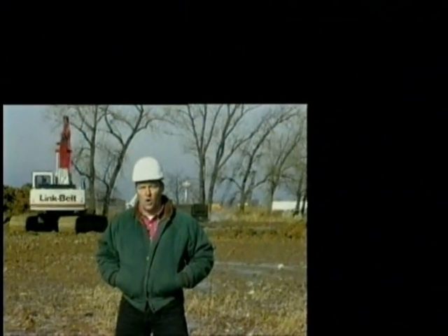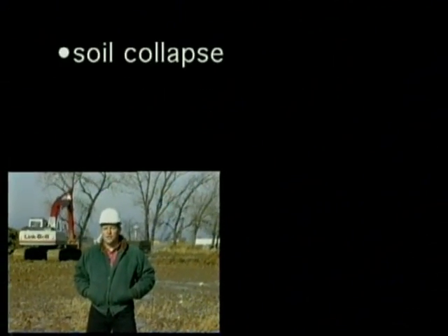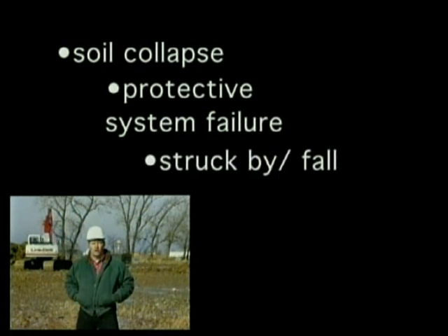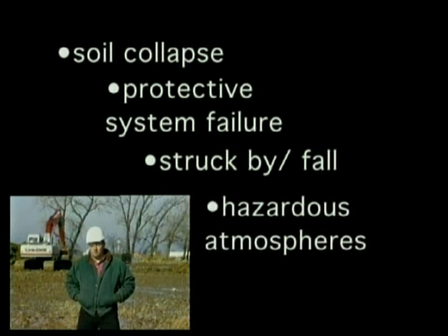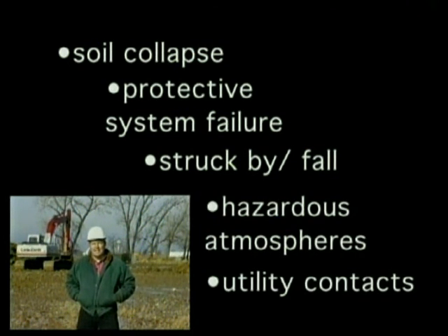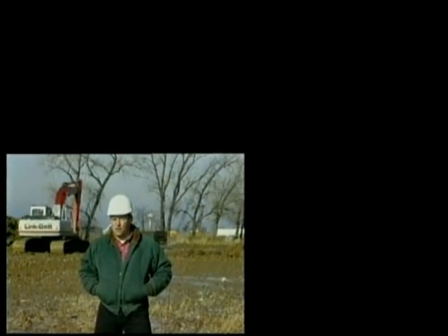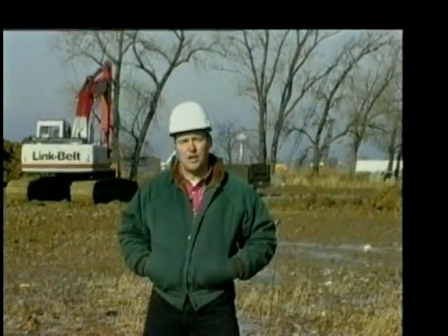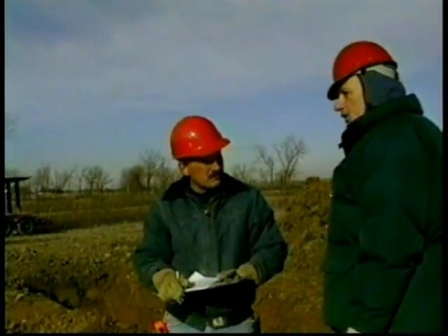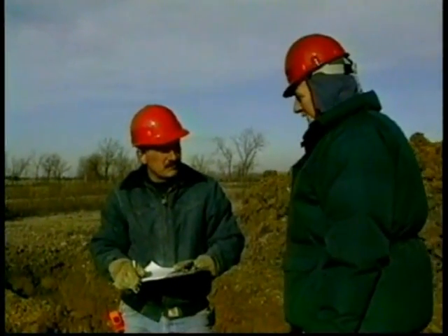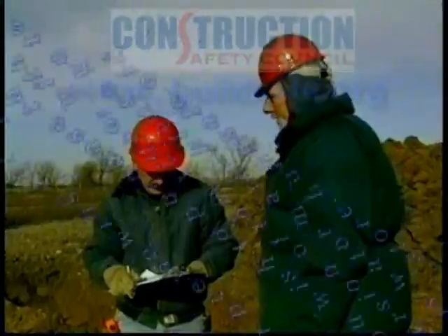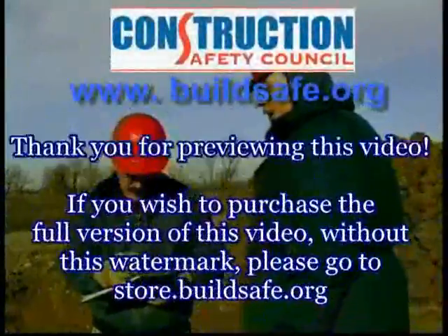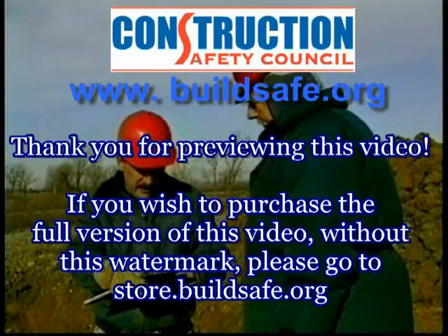Emergency situations usually occur suddenly and without warning in excavation work. Emergencies include soil collapse, protective system failure, material or equipment, or an employee falling into the excavation, hazardous atmospheres, and utility contacts. Because many fatalities occur when workers improperly try to rescue co-workers, every construction site should have an emergency action plan. The competent person should contact the contractor to become familiar with the proper procedures to be followed in the event of such an emergency and inform all employees of these procedures.